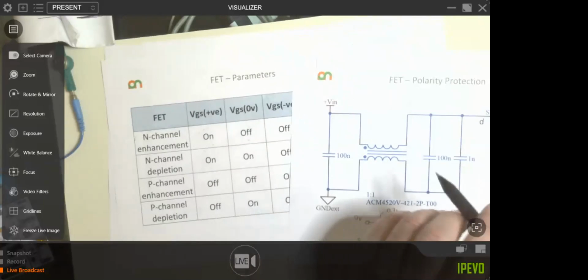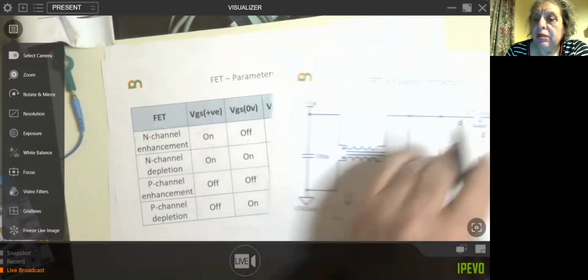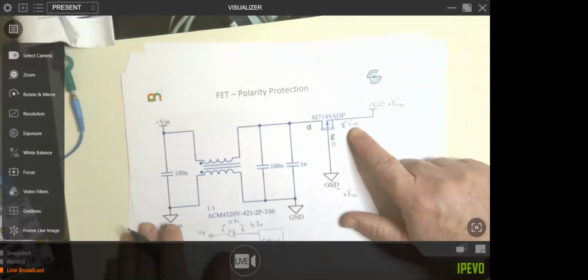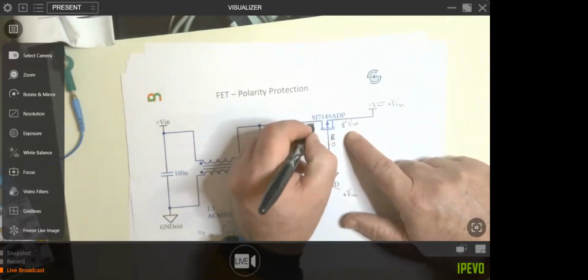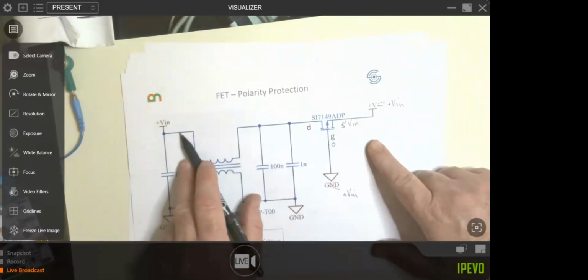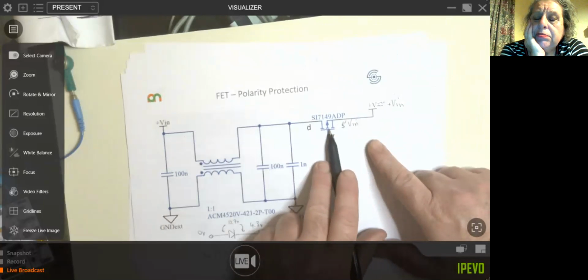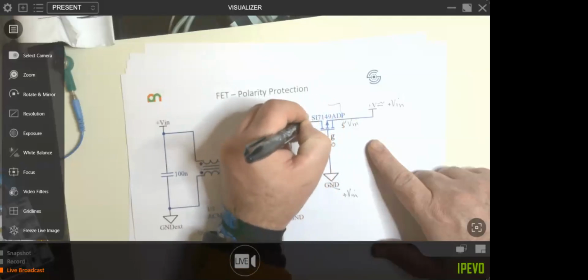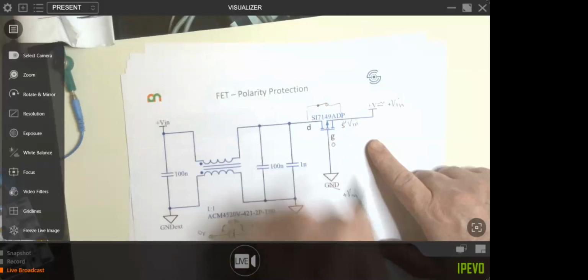And we want that to be V in. Oh, back on page, I realised that. So we want that to be V in, and that to be 0 volts, in which case we want this device to be on, like a switch. In order for the source to be the same as the input, we want it to be on.